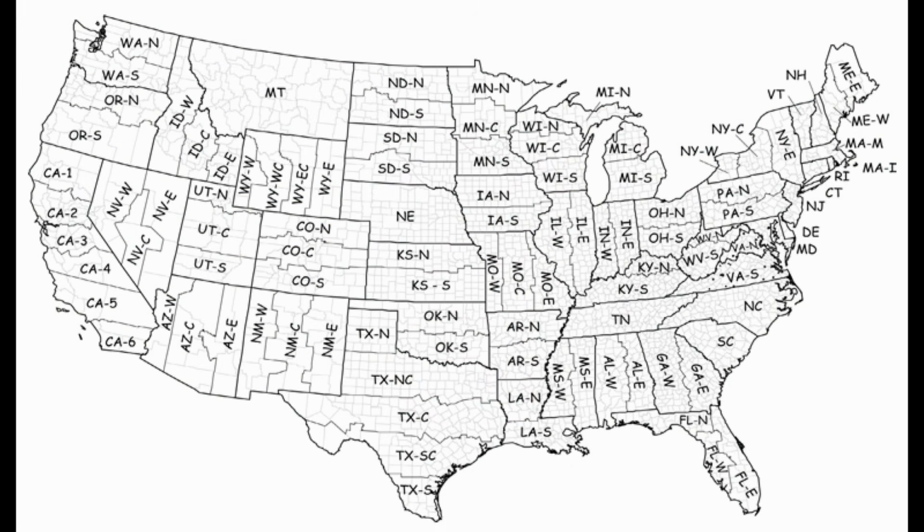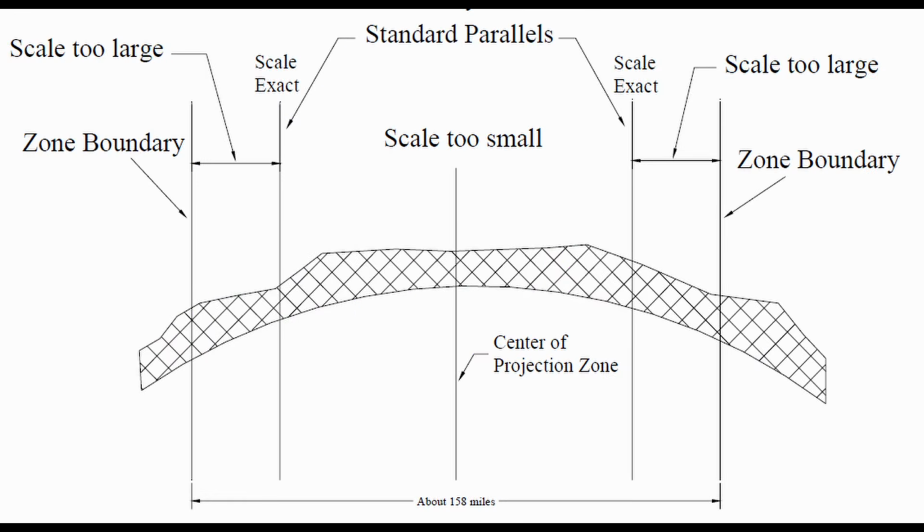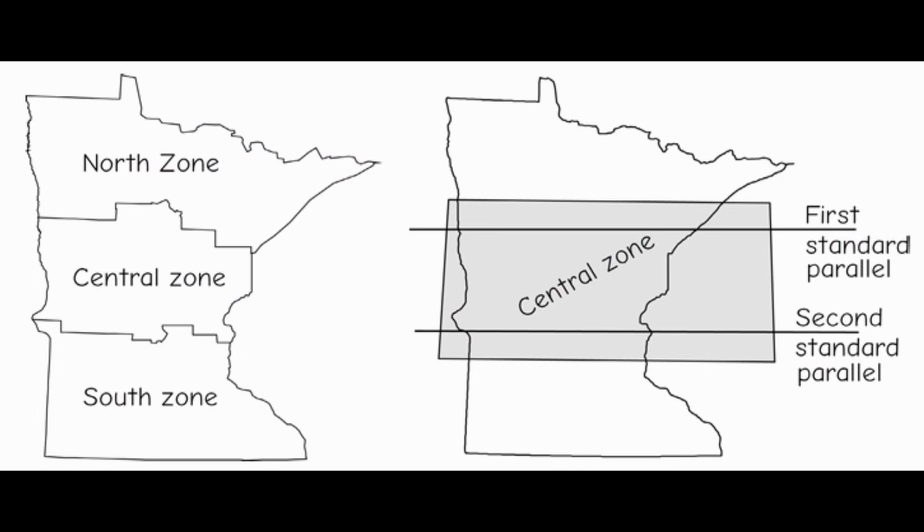When the state plane map projections were initially established, they were done so in a way that the maximum distortion caused by the grid scale factor should have been less than 1 to 10,000, with the thought being that the survey instrumentation available at the time should not produce accuracy significantly better than that, and therefore grid to ground could essentially be ignored in most situations. This was accomplished by limiting the size of map projections.